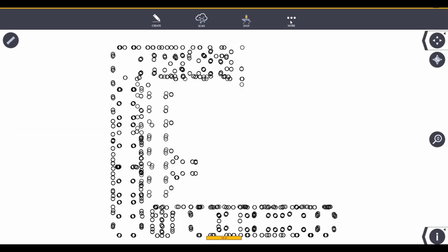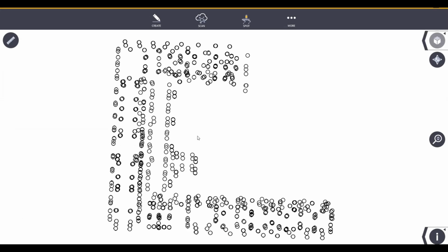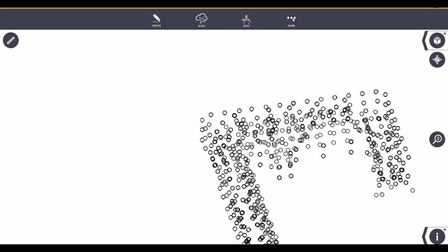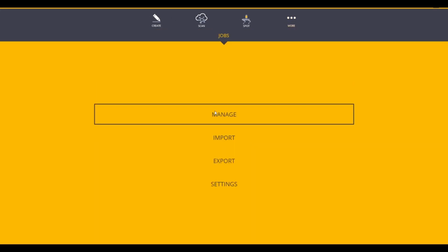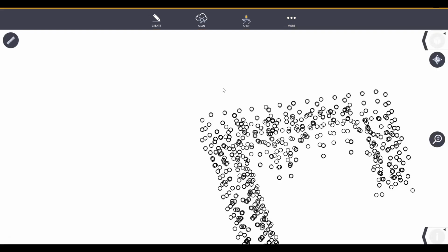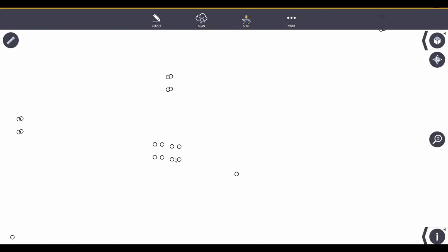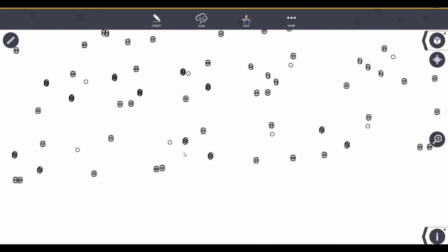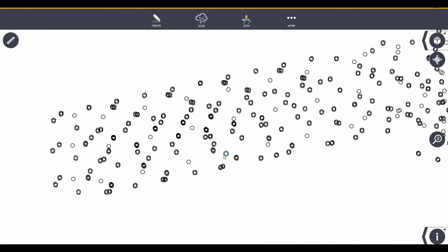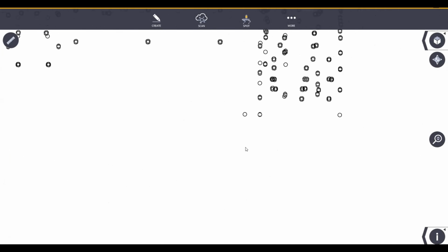As you can see, I've just gone into my Trimble Field Link software. I've gone into More, Jobs and Manage. I've then chosen this project. So this project has opened with all of these points that we have defined. We can see all those 4 around each box, as well as some single points. Now these points are going to store all of the attribute information that we installed into them.